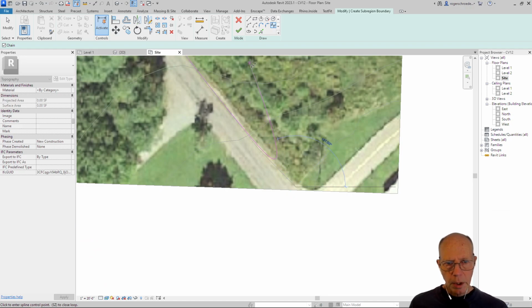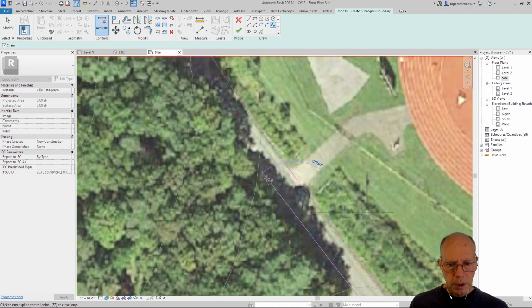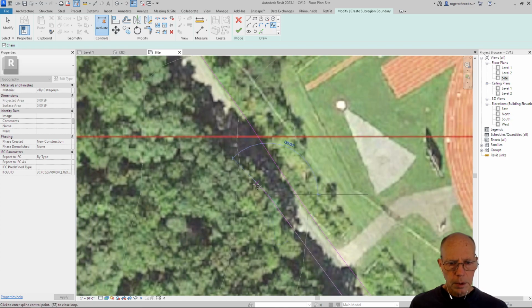And we'll just come down to the bottom, and once again, like I said, switch back to a straight line tool, and then I'm going to click back to the spline again. And now I'm really paying attention to that other line, because we know a road will just have a constant width to it. So I just want to mate it so that it has a uniformity to it, especially since we can't actually see the road in all of these locations.